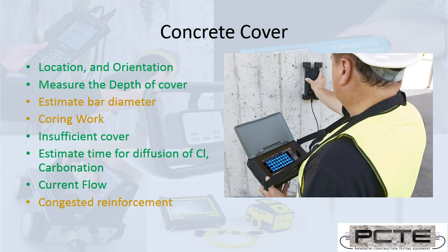They did call out in another section of the standard that it could be used to locate reinforcing before coring, where cores need to hit or miss the reinforcing. That works fairly well, but cover meters do have a depth limit. They're about 140 millimeters maximum depth penetration. So if you need to core deeper than that, it would be important to use other tools like ground penetrating radar.